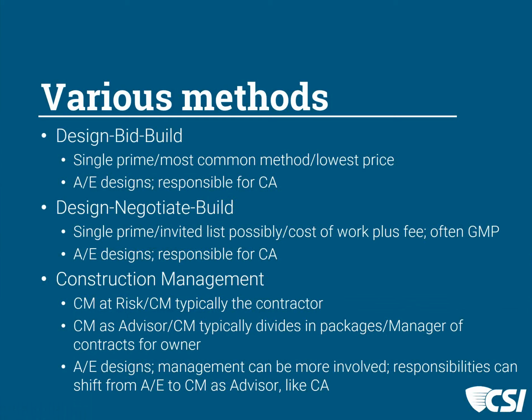In the construction management delivery method, there are variations in that delivery, whether it's construction management at risk, and typically the construction manager is a contractor, or whether it's construction management as an advisor, where the construction manager may divide the project out into different packages and manage the bidding of those packages for the owner. So there's a delivery method where it's the CM at risk or where the CM is an advisor.